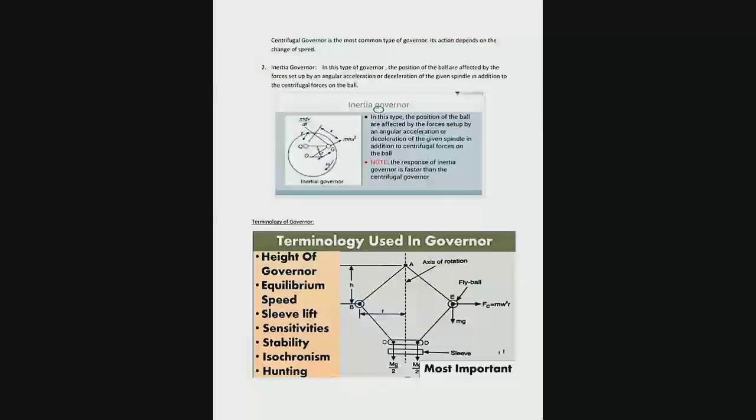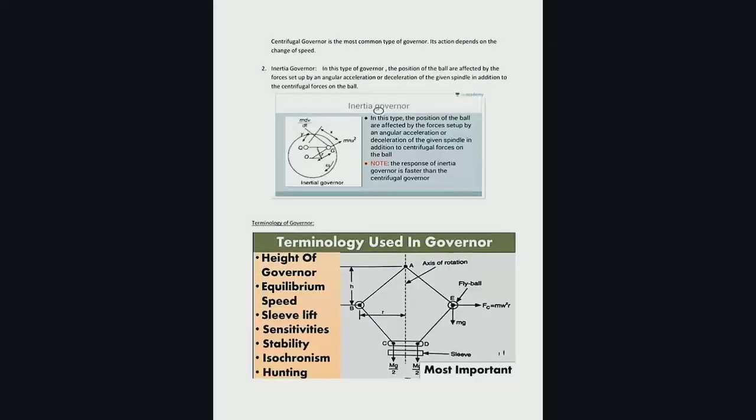Shaper machine: a shaper machine is a machine tool that uses linear relative motion between the workpiece and a single point cutting tool. It is used for removing material from a workpiece to produce a flat surface on the workpiece. Various parts of a shaper machine.